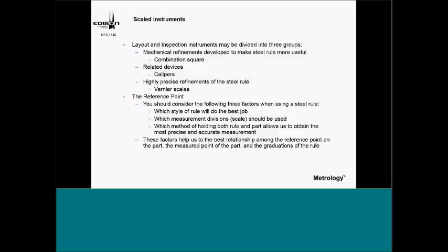Number one, what steel rule are you going to use? I have various ones that I will show. I'll have a hook scale, a smaller one, a 12-inch rule, and a 72-inch Starrett that I borrow from the company I used to work for. And then, what method of holding the rule allows us to obtain more precise and accurate measurements?